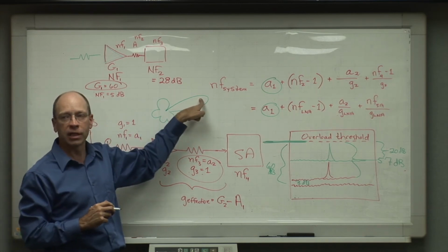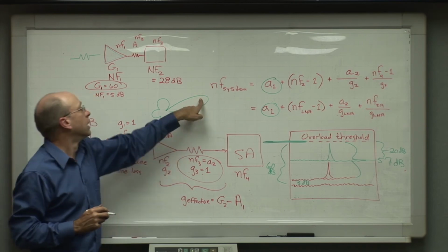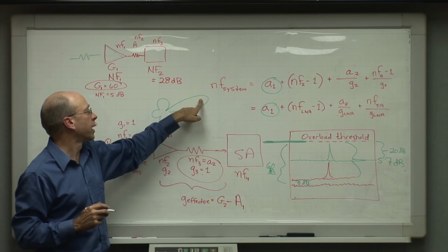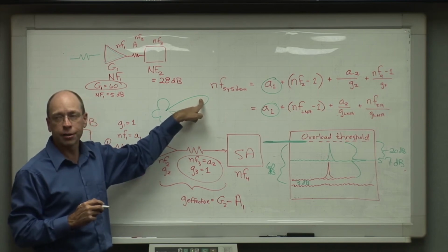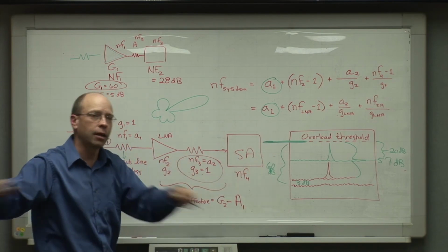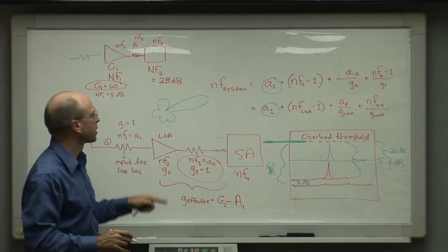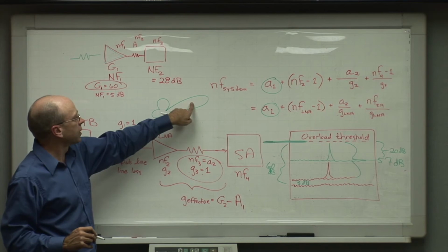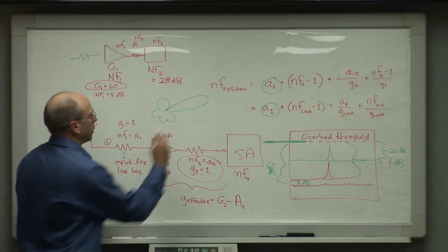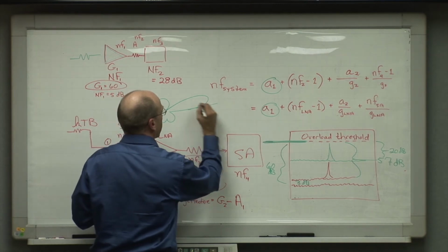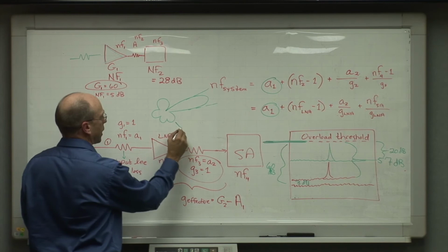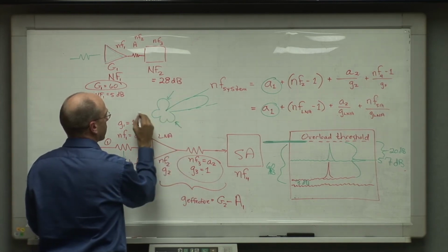of background noise level. As a matter of fact, if you're trying to look at a distributed energy source like the cosmic background radiation, or for that matter the microwave oven radiation that comes out of a big city area like, say, Chicago or Denver, Washington, D.C., the antenna, as you bring up the gain, gets more energy from the background right inside the antenna beam, but it discriminates against energy coming from all the other directions.